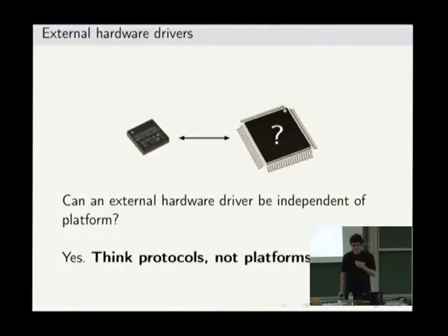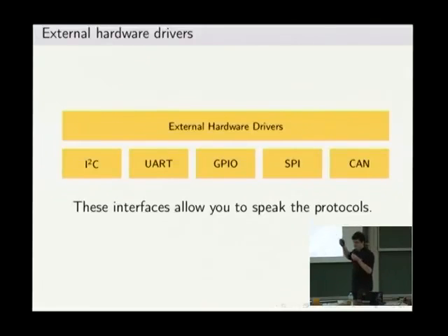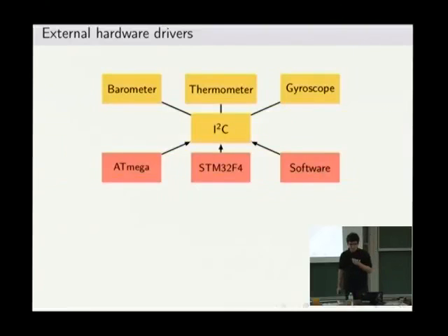So yes, you can, because you must think in protocols. This is a defined protocol. It's a distinct chip, and you can write a platform-independent driver, because we already have these interfaces. They speak these protocols, and you can build your hardware drivers on top of each other. And that's exactly what we've done in xpcc. So you have 3 devices on your I2C bus, and they only talk through this interface. And the driver doesn't care what platform it is on, because the interface is always satisfied the same way.